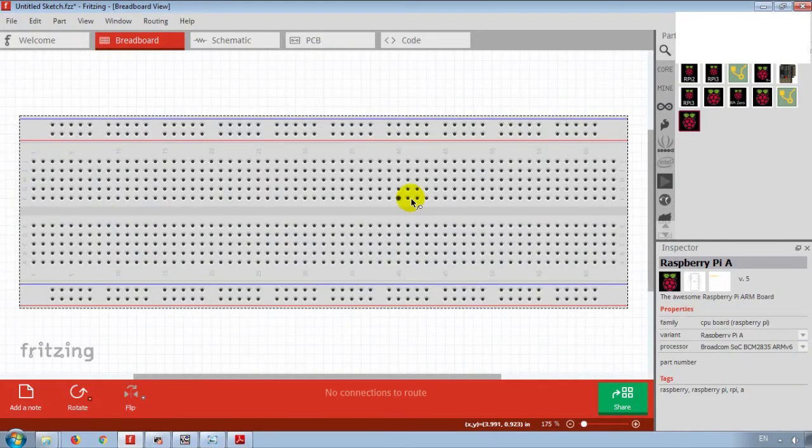So first of all, we need to have its hardware and make the circuit and then see how this circuit is going to look. And then we can find which port or which pin the LED is connected to, and then we can have access through Python and have different functions and different outputs to that pin and then turn on the LED or make it off.